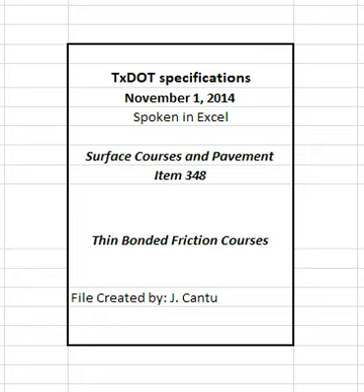The engineer will provide the mixture design when shown on the plans. The contractor may submit a new mixture design at any time during the project. The engineer will verify and approve all mixture designs, JMF1, before the contractor can begin production. Provide the engineer with a mixture design report using the department-provided template.